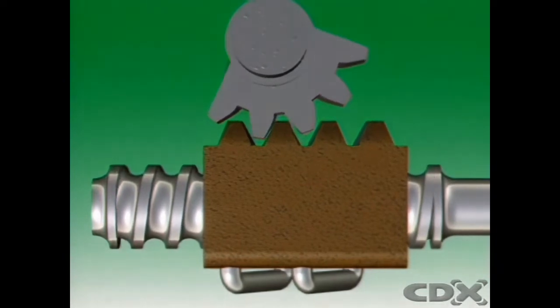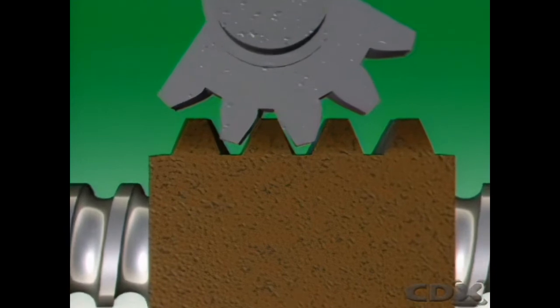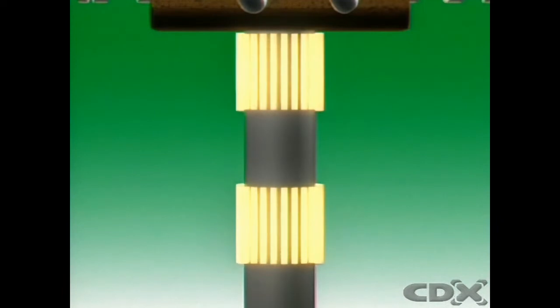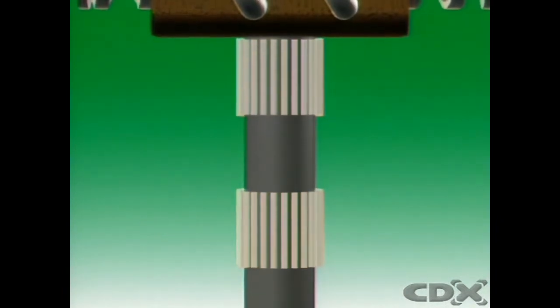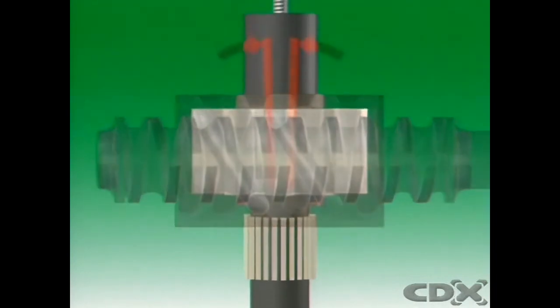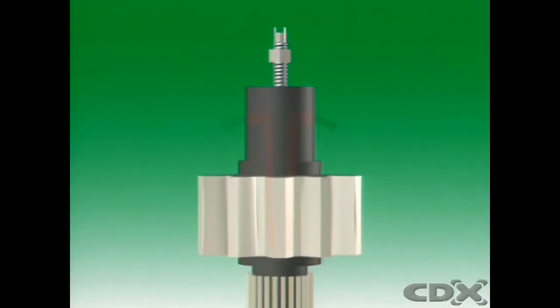The sector gear and nut teeth are designed so that when the teeth are in the straight ahead position, they have minimum clearance. This reduces free play in that position. The pitman shaft is supported by two caged needle roller bearings in the steering box housing. The sector teeth are angled, and an adjustment screw on the steering housing cover provides proper engagement of the sector gear and nut teeth.